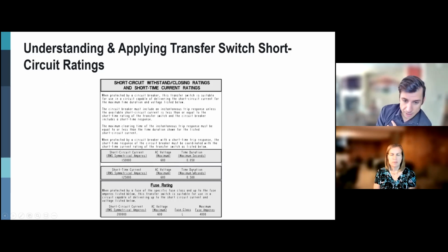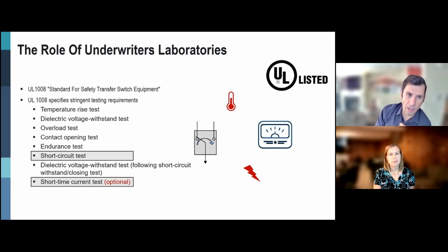So let's go ahead and describe this. Where does this information come from? The leading standard for testing transfer switches is UL 1008. It's the standard for safety for transfer switch equipment. They specify very stringent test requirements. And by the way, UL 1008 is harmonized with CSA C22.2 No. 178.1. They're very similar, with very minor differences.